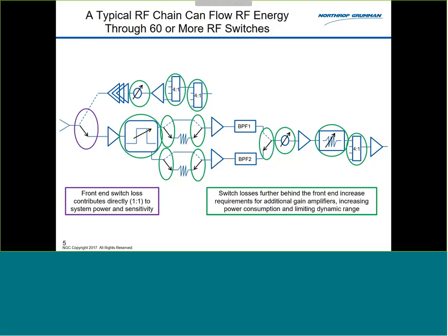You do. So just like with amplifiers, the matching networks are very important, and that's for all of these different kinds of components. So that's going to depend on your frequency range that you're operating in, and that also has to be accounted for as well. Now those can be, depends on the design, a little bit more straightforward to put into it, so that it's the switch performance that's going to limit you. But it's those matching networks that define what frequency you're expecting that switch to operate within. So the switch, the amplifier is going to take,